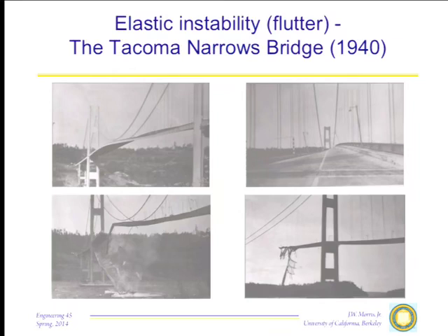If you know what's happening, it's very easy. You just put dampers of one kind or another on. In the case of a crankshaft in an engine, say an aircraft engine, there are little sets of counterweights. In fact, in some of the engines, in addition to little counterweights, they'll have a viscous damper, which is a disc inside a viscous fluid that turns around. So you just put things in.